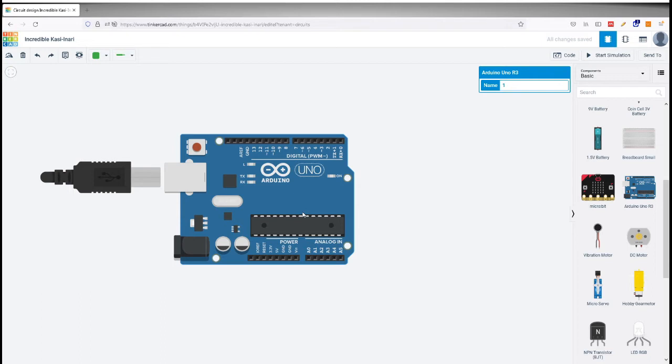So what is the next step? You need to write a small program for blinking the on-board LED present in this Arduino board. Here you can see an L is written. This is the onboard LED which is already connected to the Arduino Uno board. In the Arduino Uno board, you can see the microcontroller. This IC is an ATmega8 or ATmega328, depending on which board you have purchased.